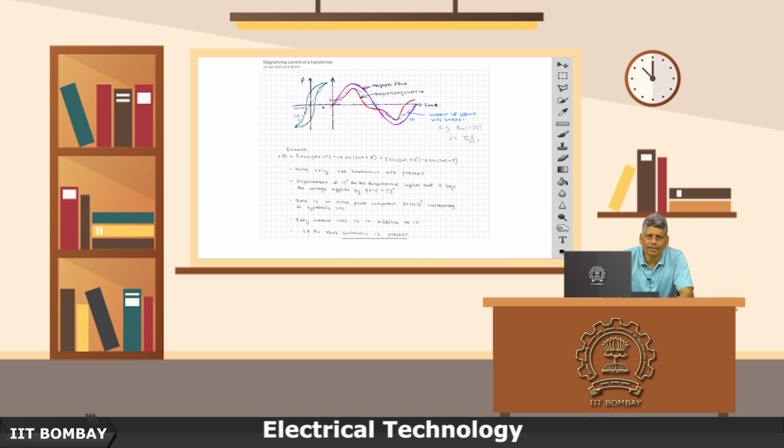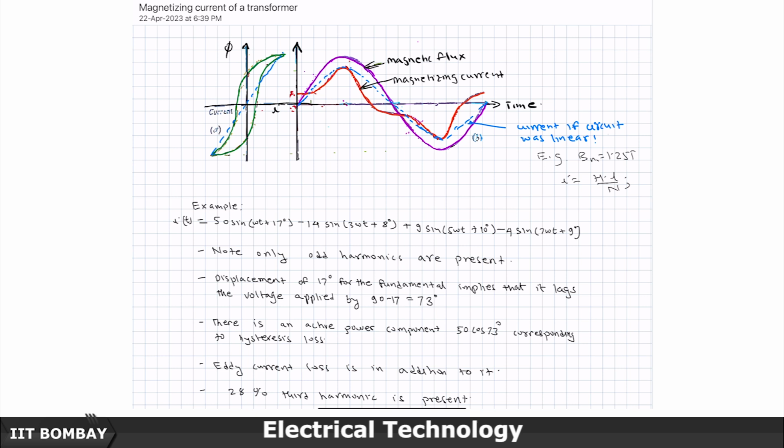The other aspect that I want to discuss is inrush current. That is also a very specific phenomenon associated with the transformer. When you energize the transformer, as the word inrush signifies, there would be a heavy rush of current, and then that current would gradually come down to your no load current.